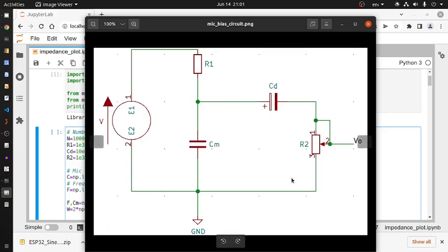To remove the DC component, this DC blocking capacitor is used, and to get the output from there we have used one resistor, across which the voltage drop will be taken to any circuit where we want to amplify this analog voltage, which is coming across this variable capacitor offered by the mic condenser.